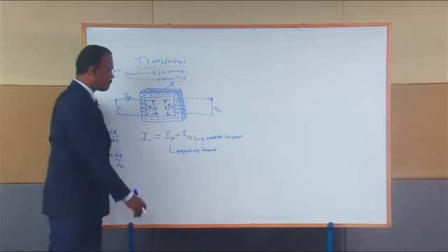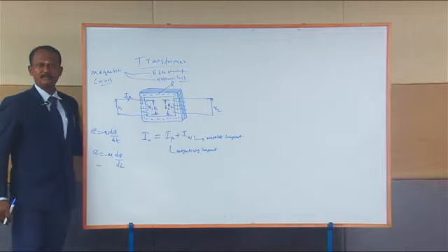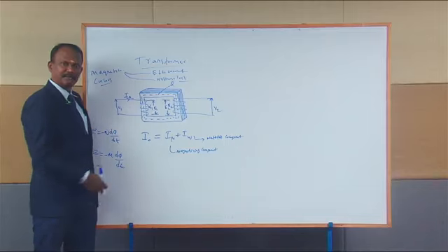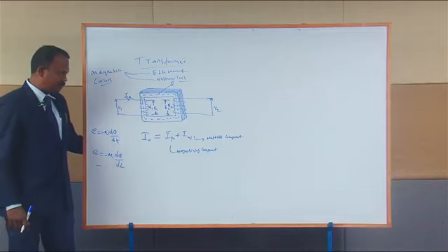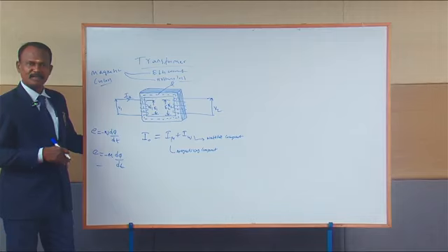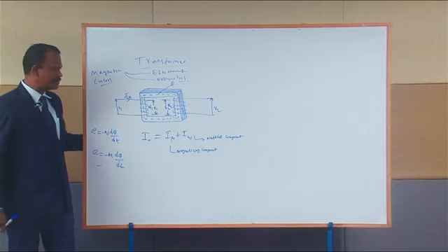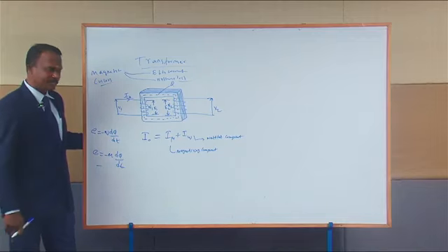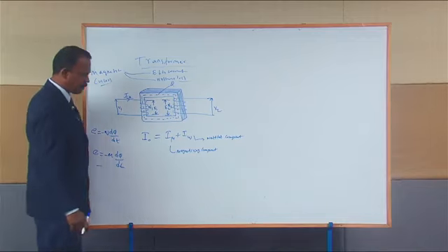It means I mu is a current which is responsible for circulating the magnetic flux through the magnetic core, and IW is a wattful component of the current I0, which delivers the energy required for the particular circuit for establishing the magnetic flux.